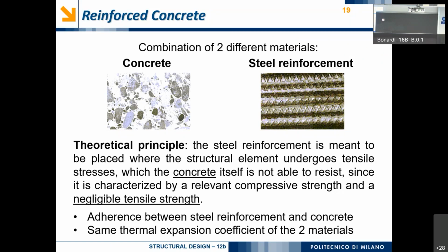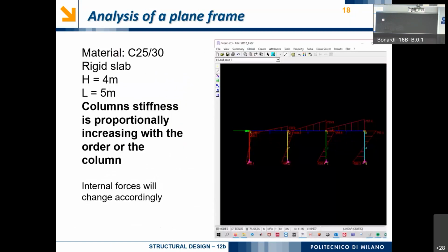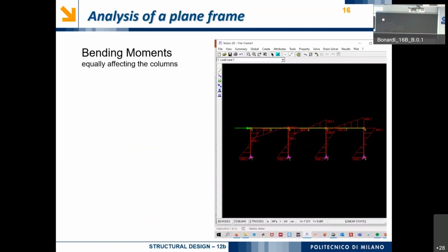Can you explain the thing about the bolt connection, how it's similar to this? Okay, sure. That refers to the first case. This is the traditional way we can model a bolted connection. We have some force applied to the structure, and all the elements that oppose that force have the same stiffness. That means the load is distributed homogeneously along all the elements.